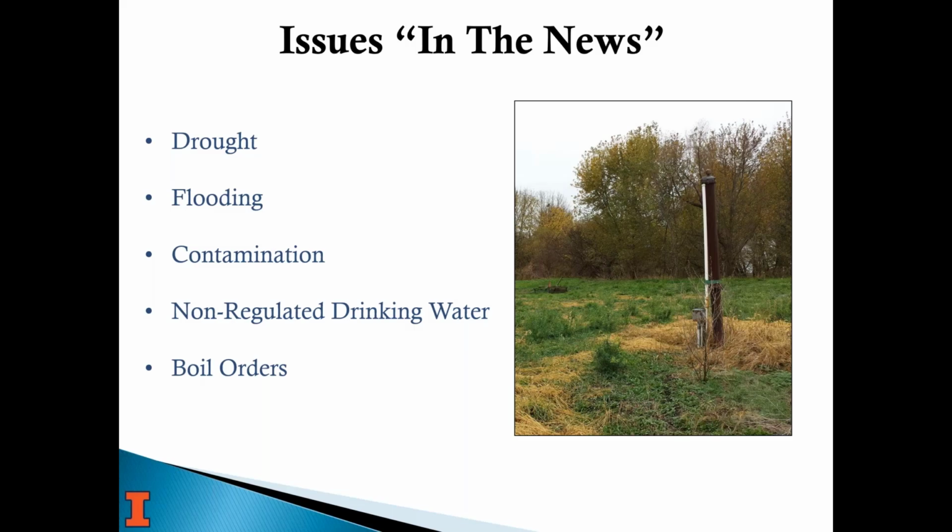I mentioned boilers here because I work a lot with water operators as well, and especially in some small towns, if they have a main break and they have to issue a boil order where they fix the pipe, that's because it means that things can get into the water line when the pipe's broken. And so to protect all the customers and protect our health, they have to issue a boil order for that area whenever the pressure is not maintained in the system. But that has nothing to do with the aquifer or a well.